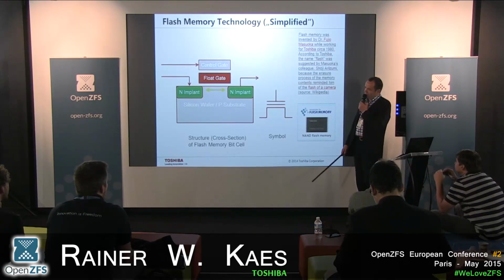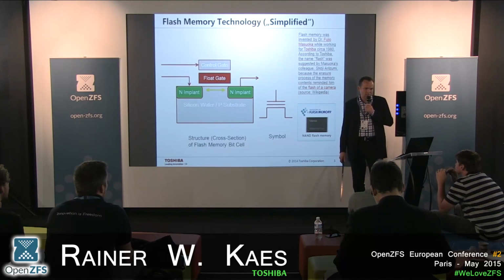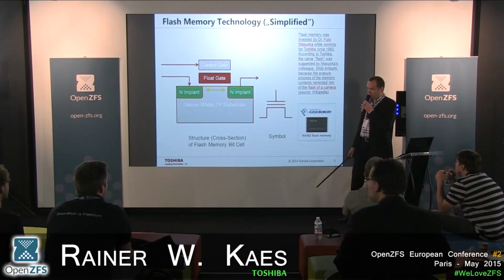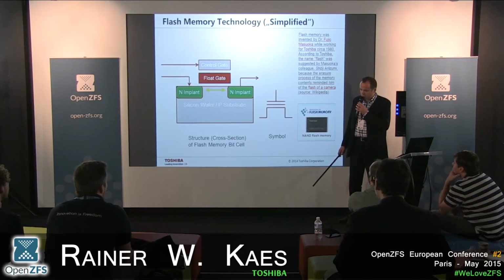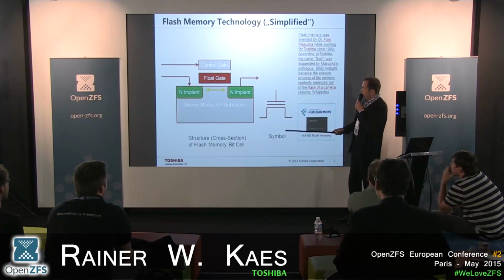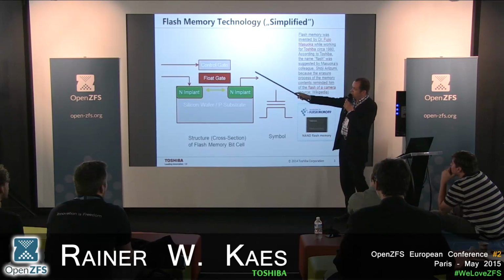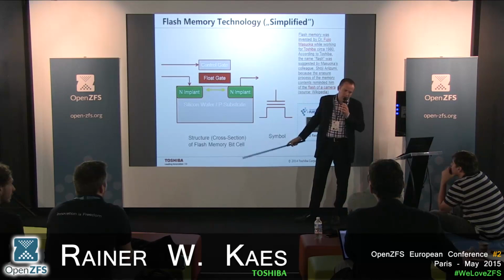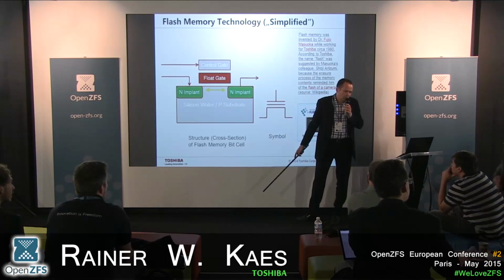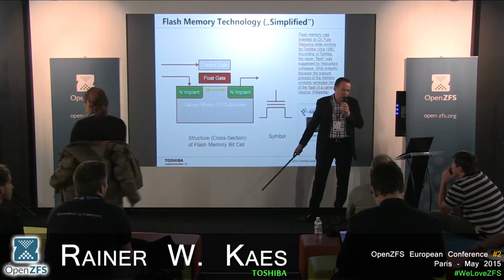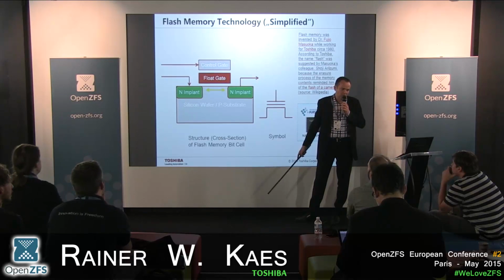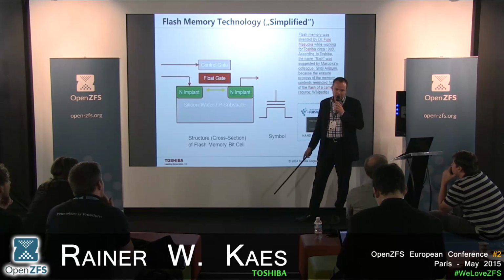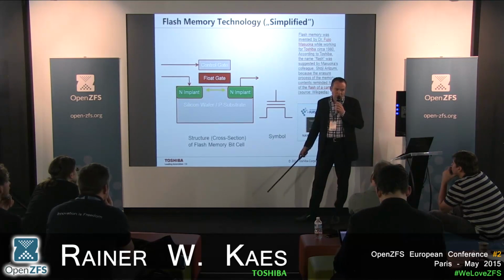So, diving very deep into the flash memory technology. In an SSD, we are using as the storage component the NAND flash. It's a kind of semiconductor storage, and this is a very simplified cross-section of a single NAND flash memory cell. I'm explaining it simplified, in a way targeted to the understanding we need. A semiconductor technologist would say it is too simplified or maybe wrong, but just keep in mind, we need to develop a model for us to understand.